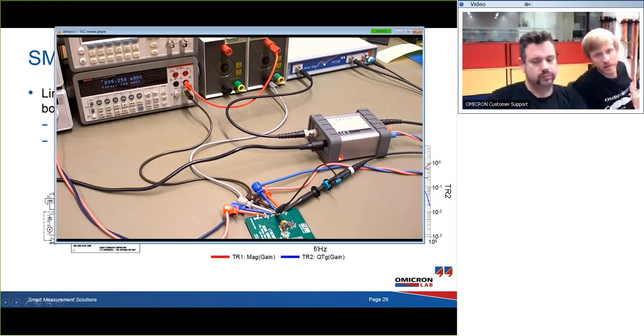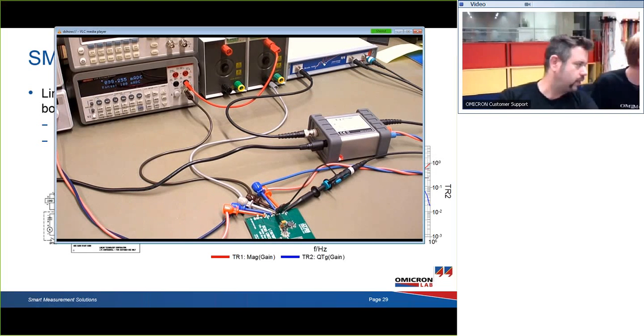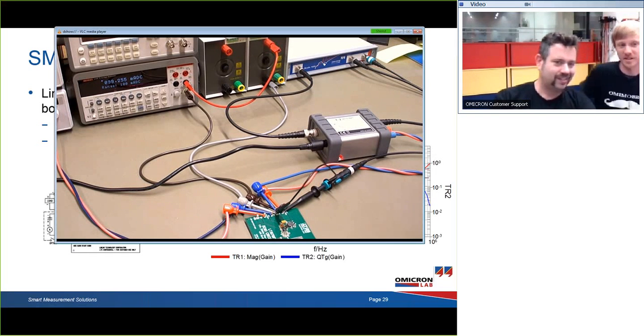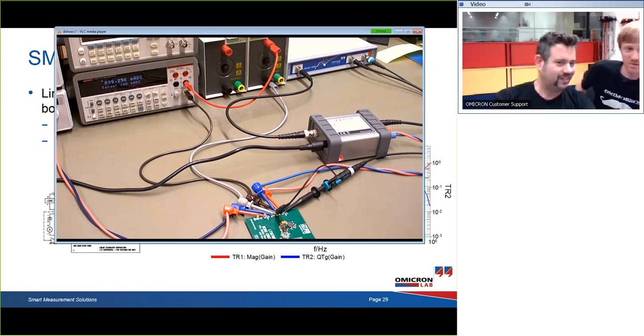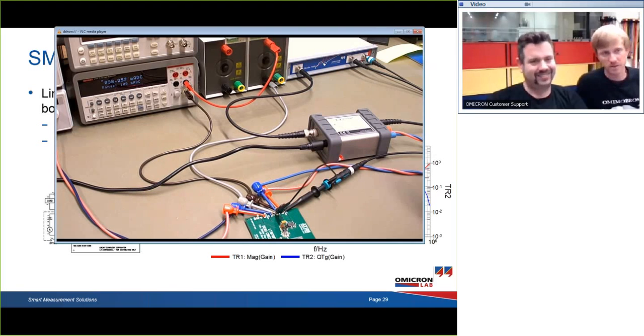On the left-hand side of the picture, you can see that we are currently loading the circuit in addition to the current injector with 99.2 milliamps, so 100 milliamps over our load resistor. Why are we only using 100 milliamps when this thing can do 1.5? Here I have to cite Steve, and he always said no load is no good. This circuit shows its worst stability at low load conditions, so we set the load to a low load condition.